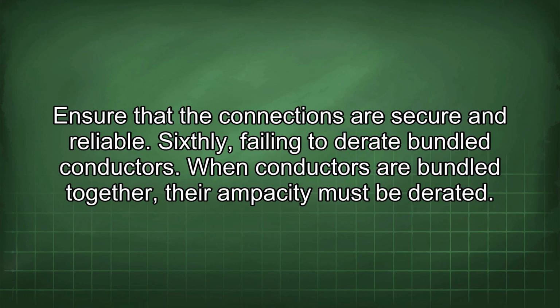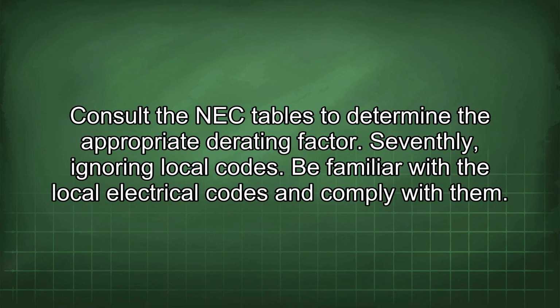Sixthly, failing to derate bundled conductors. When conductors are bundled together, their ampacity must be derated. Consult the NEC tables to determine the appropriate derating factor.